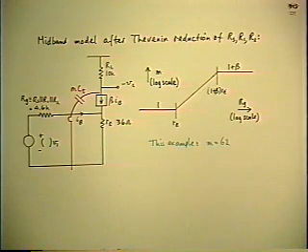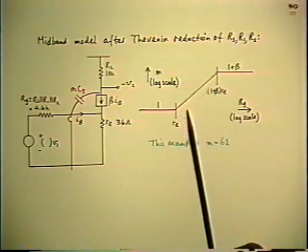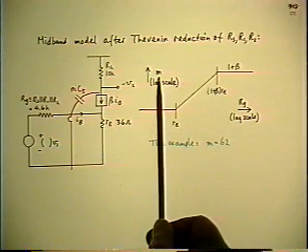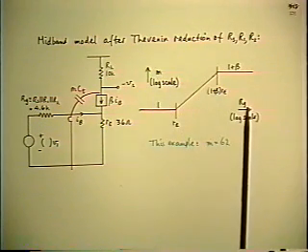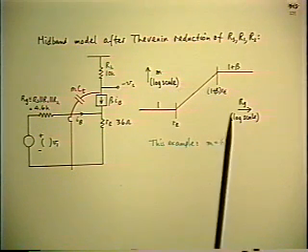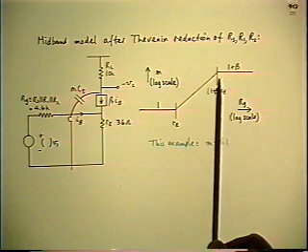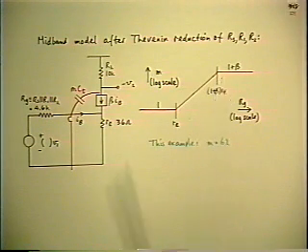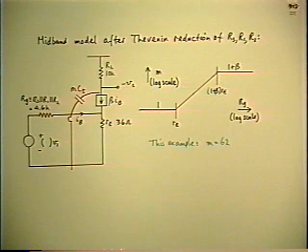One refinement about it also. These represent asymptotes, of course, and the actual function, M as a function of RG, has smooth corners, just like the frequency response really does. In frequency response, remember the actual curve is 3 dB away from the asymptote intersection. In this case, the smooth curve is 6 dB away from the asymptote intersection. Why is there a difference?